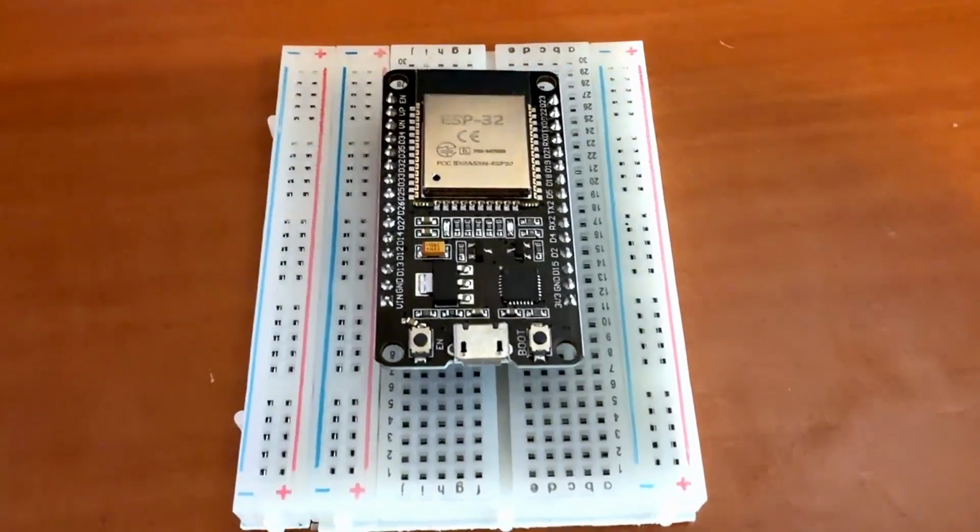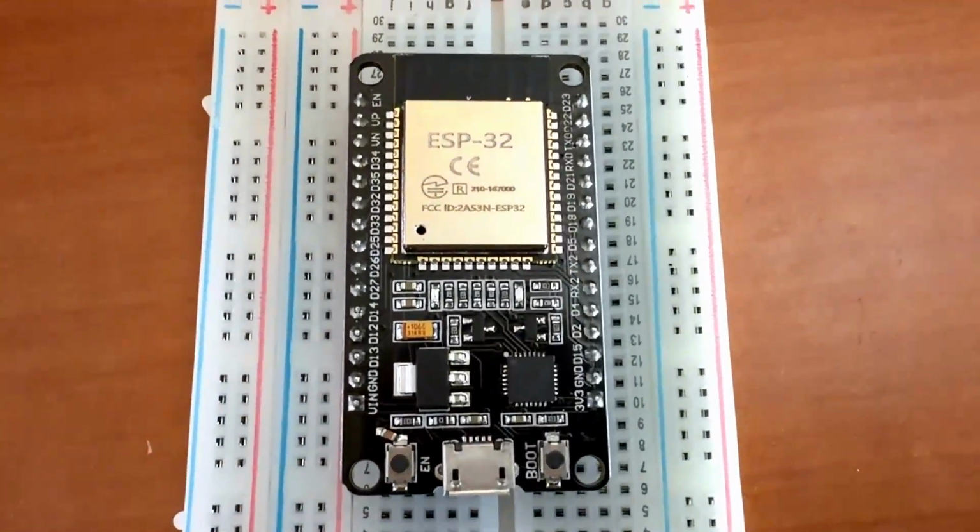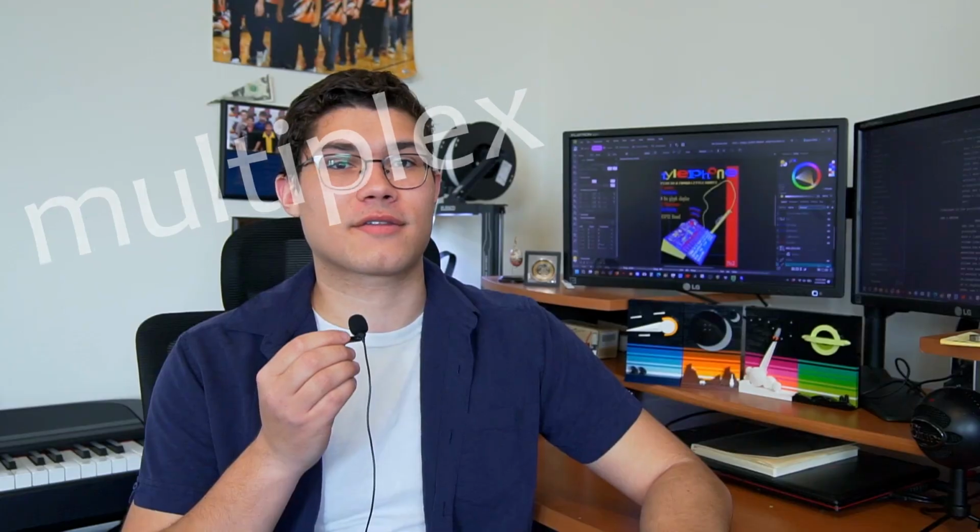Now, I have a problem. My ESP32 only has so many pins, and I've actually run out. I can only turn on 4 of the 7 LEDs of my display. I could multiplex, whatever that is. I could use I²C or do some kind of matrix thing for the keys of the keyboard, but frankly, I don't want to. I just want to keep things simple, and I honestly like the design constraint. There are a surprising number of things you can do with just 4 LEDs, and I honestly think I can make a whole user interface. Let's just use 4 and let's get to prototyping.